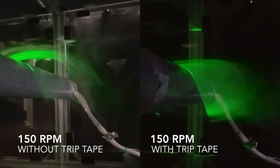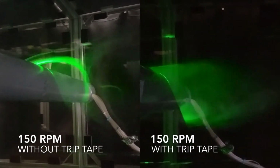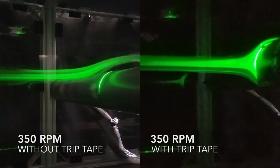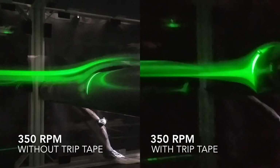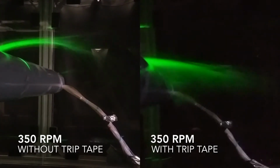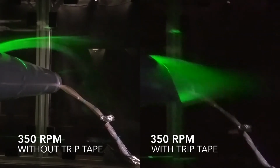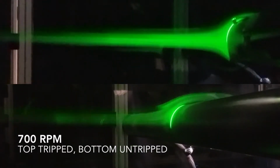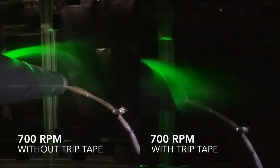Capturing the flow at 5 meters per second provided the most visible flow patterns. However, the Reynolds number is too low for the pressure readings to provide any meaningful data. At 14 meters per second, it can be clearly seen that the trip tape creates turbulent flow within the boundary layer, and the flow becomes more attached to the cylinder. Increasing the velocity to 30 meters per second caused the most attached flow out of all three velocities when the trip tape was being used.